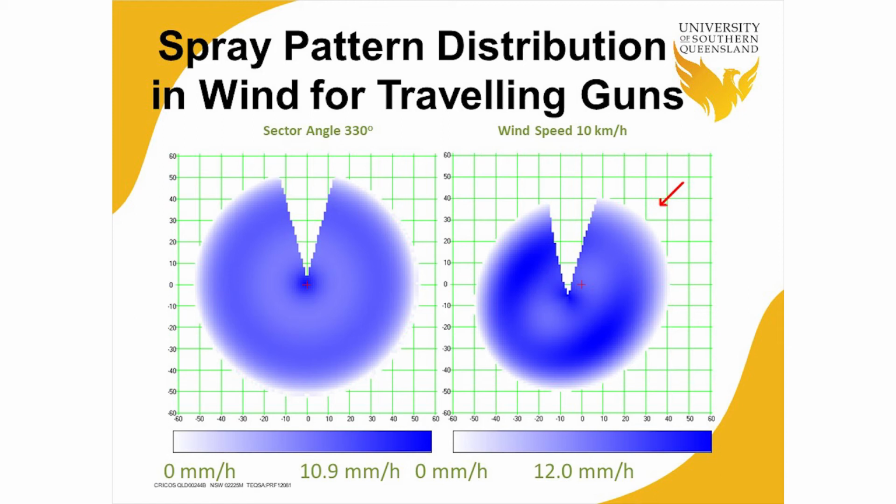And in the last 5 years we've done significant work towards improving the performance of end-gun systems on centre pivots using the same sort of ballistic sprinkler modelling technology to actually allow people to understand the variation in the water depths being applied by these systems. And that's another package that's available to assist you to improve irrigation performance.